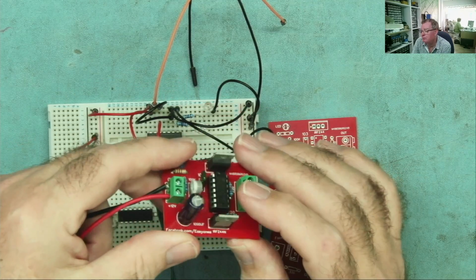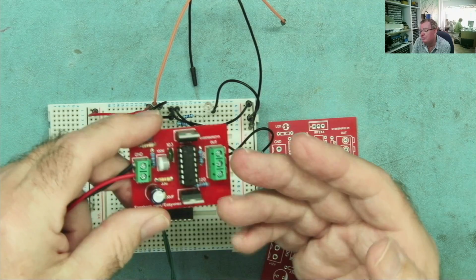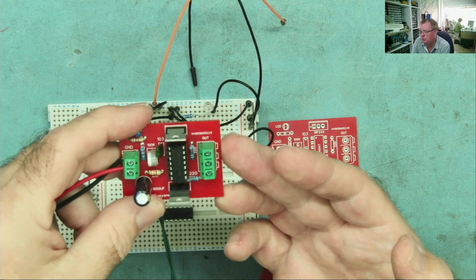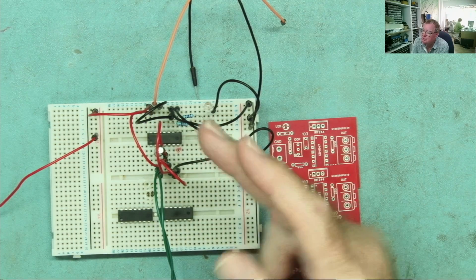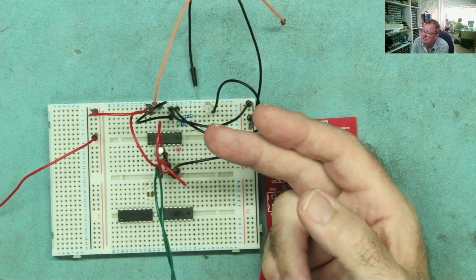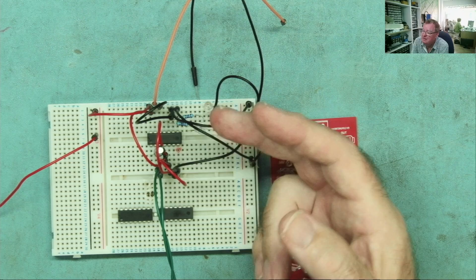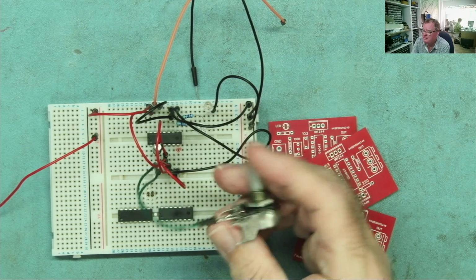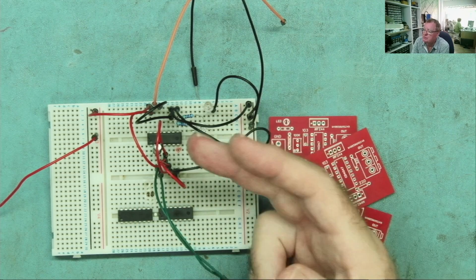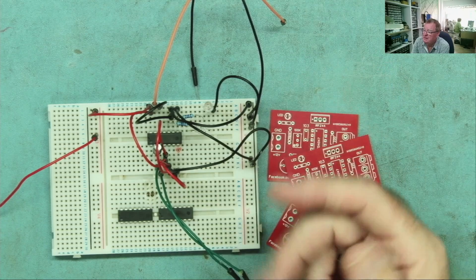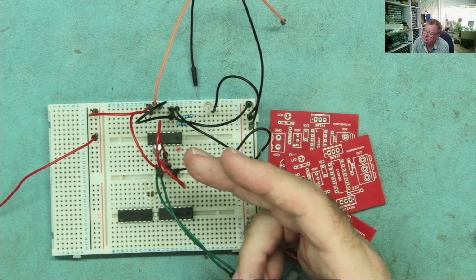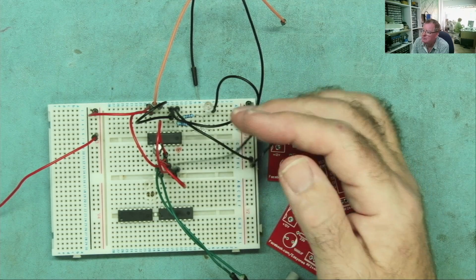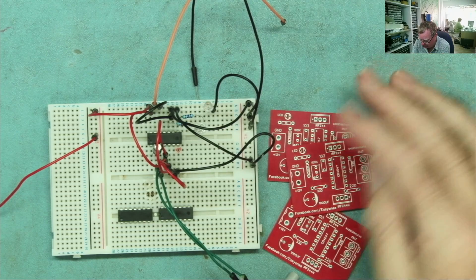I then tried 3 other chips, all doing the same thing, so it does seem very strange. I would have a whole batch of faulty chips, for example. So I then built another circuit. This is not the same. It doesn't have the MOSFETs, you can see. This is an LED flasher. So again, it has a capacitor, a variable resistor. This is set to run at a lower frequency with a higher value capacitor, and it should flash the LEDs alternately. Again, it doesn't. The oscillator runs, but the outputs on pins 10 and 11 don't work. Sometimes it will go from one state to the other and stick there, but that's what we get.